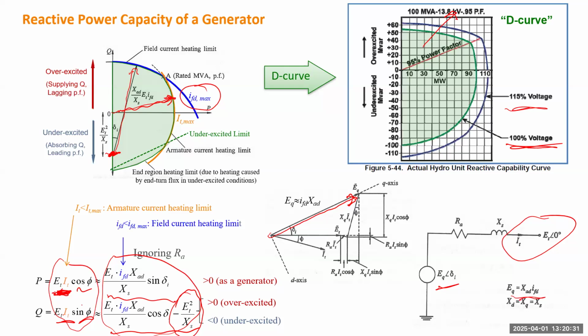So the field winding limit will react. Either it tries to hold the current at that value, or it may trip the unit. If it holds at that value, the Q cannot increase further, it will stop there. If the unit is tripped, you're going to lose this VAR source, because the generator is also a VAR source. You have even worse voltage, right?